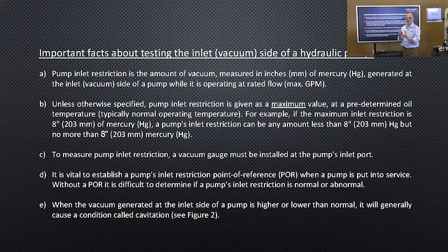The problem with designing with hydraulic pumps is that no two identical pumps have the same inlet restriction in different applications. For example, engineer A may mount the pump above the oil level, and engineer B may mount the same pump below the oil level. Engineer A may put a suction screen in the tank, and engineer B may not. Engineer A may have a 90-degree bend going into the pump, and engineer B may not. That's why every single hydraulic pump in every application has a unique set of operating parameters with respect to inlet restriction.